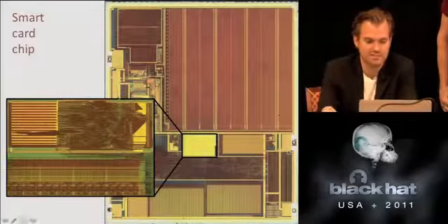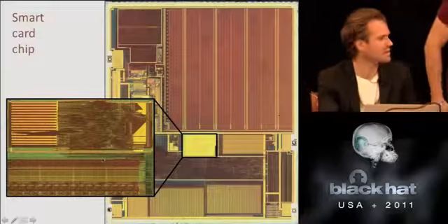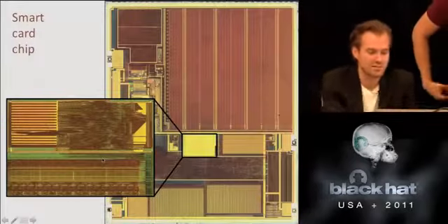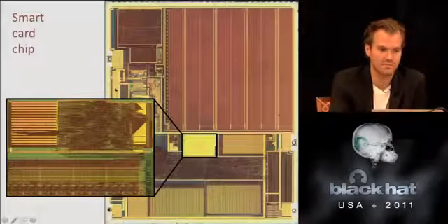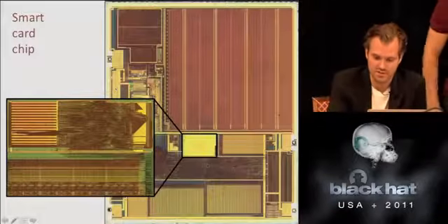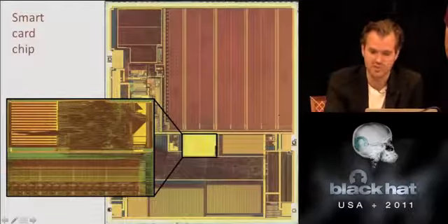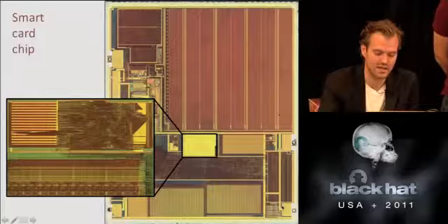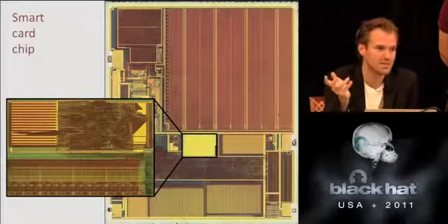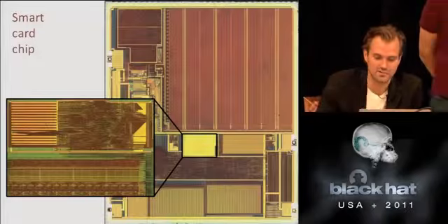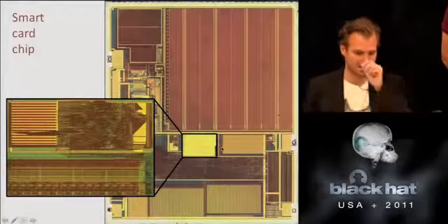And since this processor core is really, really slow, it's maybe 20 megahertz, 15 megahertz at 8 bits, it has some supplementary coprocessors. So in here, you'll find an AES engine, I believe. Some others come with ECC accelerators, RSA, and so forth. So the crucial operations they do very fast, and everything else around it kind of slow. So that's the smart card in a nutshell.